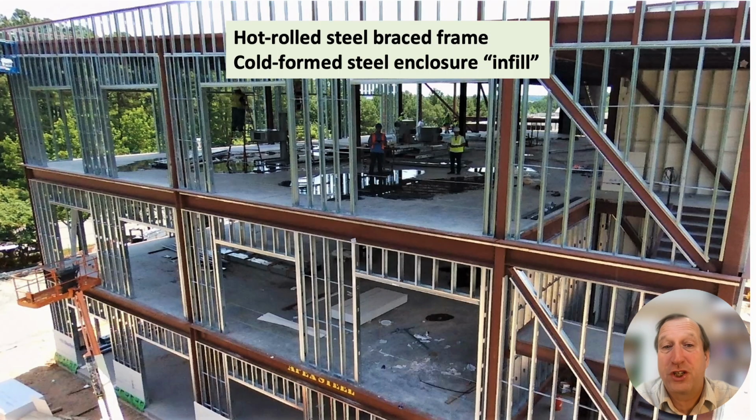So you see the image there was with concrete. This is an image of a steel framed system. You can see the bracing, the hot rolled red steel, the beams around the perimeter, and the infill, non-load bearing. It doesn't take any gravity loads. It doesn't take any lateral loads. What it does is it collects the wind loads out of plane and transfers them to the beam above and the beam below, or the floor above and the floor below. That's its job. It also supports the weight of the eventual enclosure finishes. So it has structural requirements, but at a very low level. Like a door has a structural requirement.